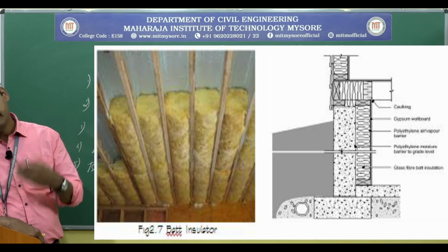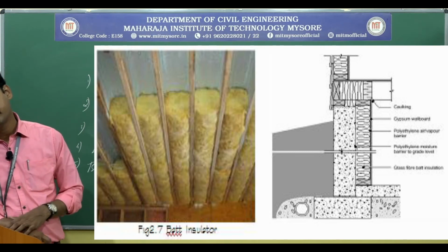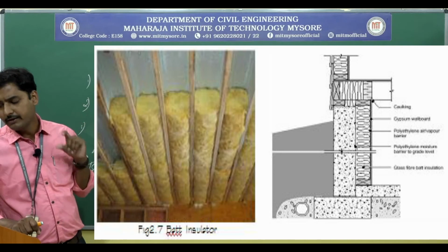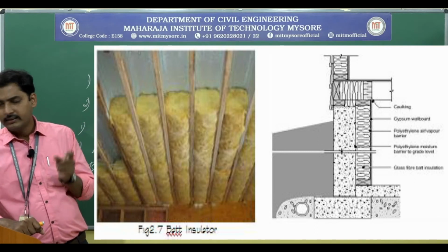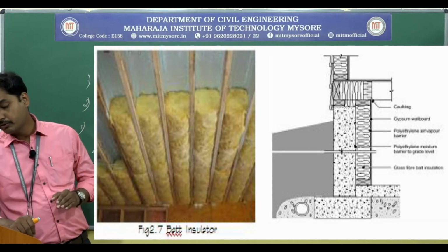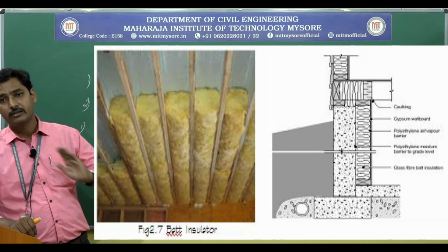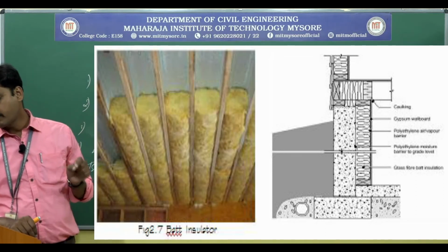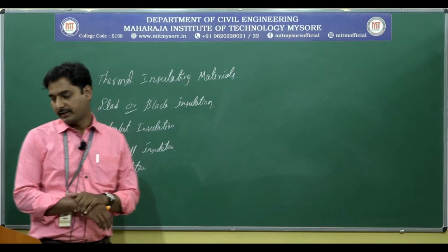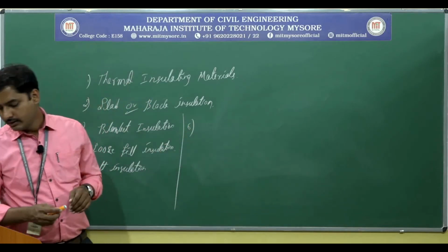On above we can have a slab, it might be of wood or of screed concreting or lightweight concrete. Below that there is a huge bed of insulation, done with a uniform thickness and at a uniform interval. You can observe the interval between those rafters is similar. The rafters are running throughout the entire length. In between we fill up the insulating materials. This is regarding the bat insulation technique. So, the next one is insulating board.